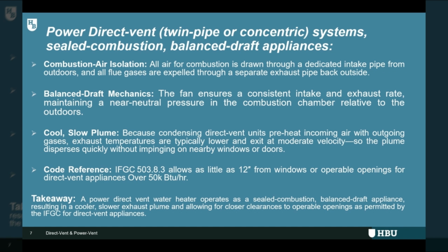Second, balanced draft mechanics. In power direct vent systems, the fan ensures a consistent and equal flow of air both into the appliance and out through the exhaust. This maintains a near neutral pressure within the combustion chamber relative to the outside atmosphere. So, there's no significant pressure pushing exhaust gases outward.